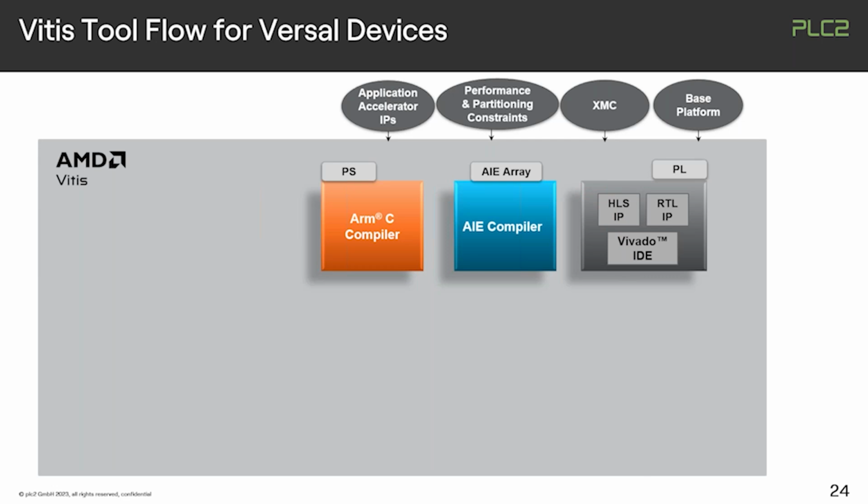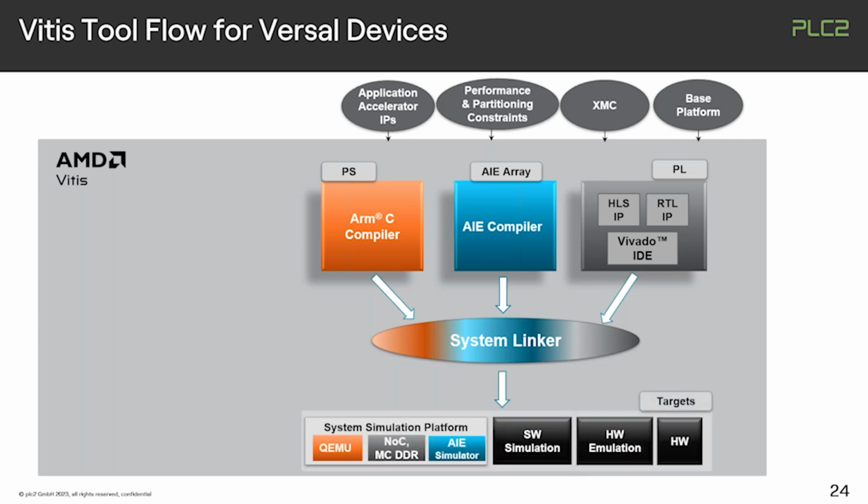And that all needs to come together on the software-defined layer. There's a linking step, as Xilinx calls it. It's the V++ linker that's used there, that is aware of these elements and the way that they should be connected, and it rearranges the top level and then finally builds the complete image. So that's what we are looking at in this context.